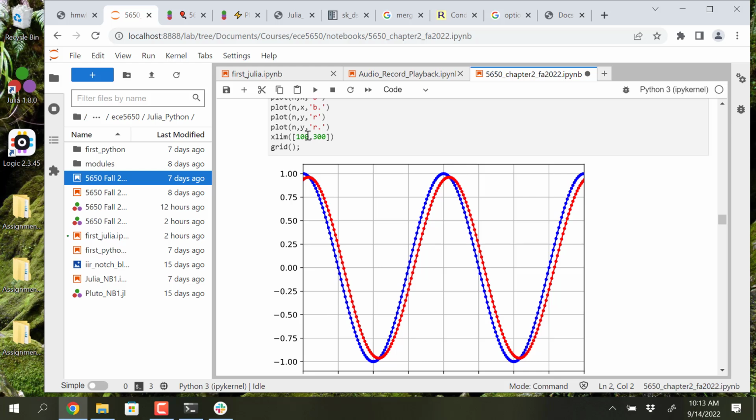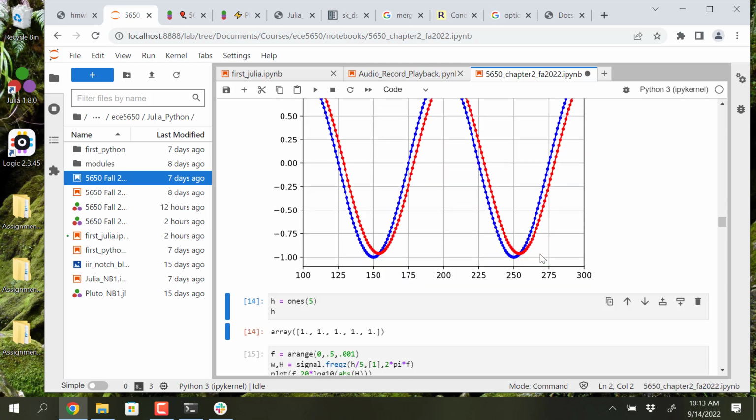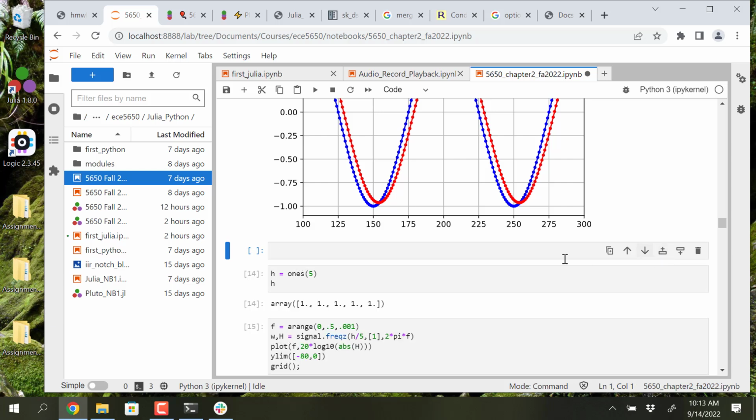You could observe the phase shift at this frequency if you just looked at the zero crossing difference, say right in here, and then took into account how many samples are in one period, and then you could get the phase shift, right? And that should match the phase shift. And if we wanted to get the phase shift,